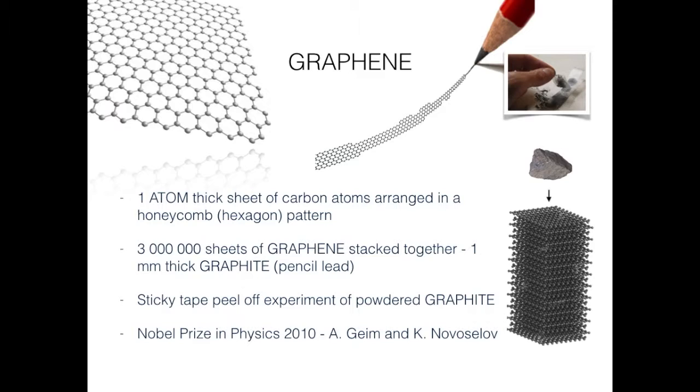two-dimensional atomic layer of hexagonally packed carbon atoms, a single sheet of graphene. The Scotch tape technique that Nobel Prize-winning Manchester group scientists André Geim and Konstantin Novoselov used to discover graphene is very simple. Starting with powdered graphite obtained from, say, a HB pencil lead, it is possible to peel off individual layers of graphene from graphite using common sticky tape. When the powdered graphite disappears from naked-eye visibility on the transparent tape, you can put it under the microscope and see the pieces of graphene crystal.